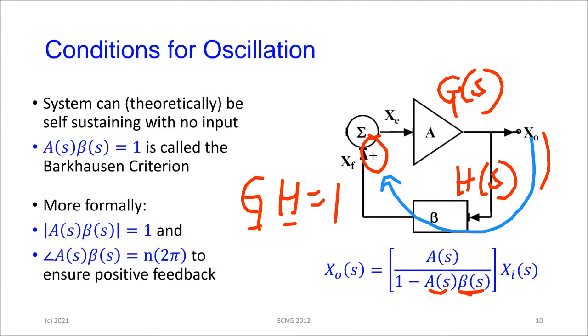But if you have other components in there somewhere, then you have to have a way of figuring between A and β to make sure that the entire phase shift as you go around the network is a multiple of 2π, so that whatever you are feeding back is totally in phase with whatever is being generated inside of the system, so that it continues reinforcing itself.